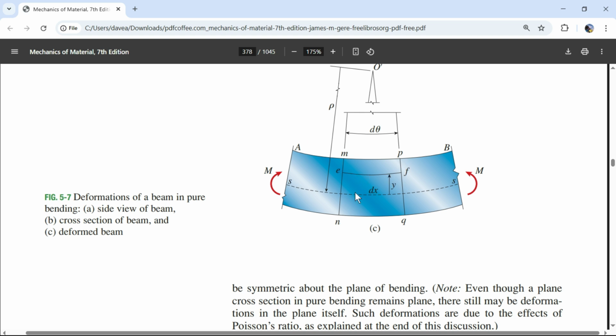Cool. So now that gives me something to work with, because I said if this was steel and something had a change in length of 0.2%, then we're basically at the limit. So this picture is highly exaggerated, and that's good to point out, where we have to use highly exaggerated pictures to show these curves, to show these changes in lengths, just to get a mental idea of what's going on.